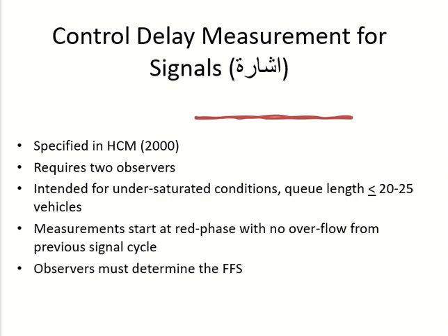So both these conditions are saying that for your study, the queue should not be too long. How do I know if it is too long? You have 2 criteria here. The first criterion is you actually see how many cars are in the queue. If there are more than 20, it's too long. The second criterion is if you see cars coming during green, but before they cross, the signal becomes red. This is called overflow, and this is also an indication the queue is very long. Clear?